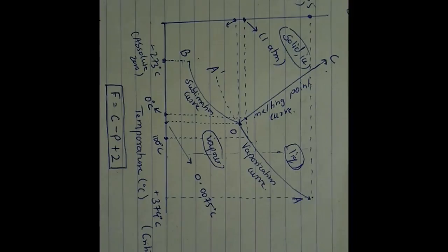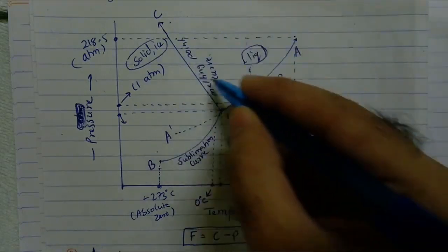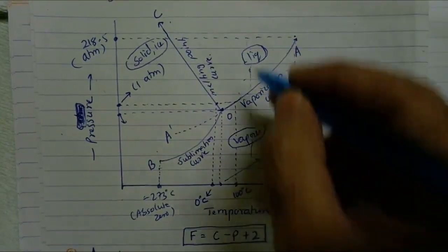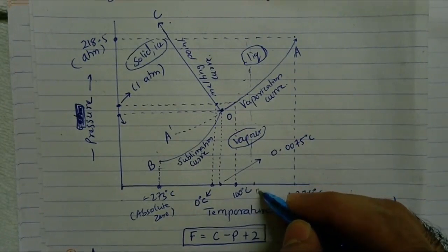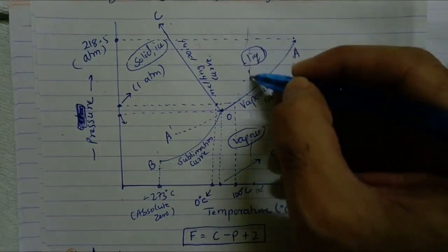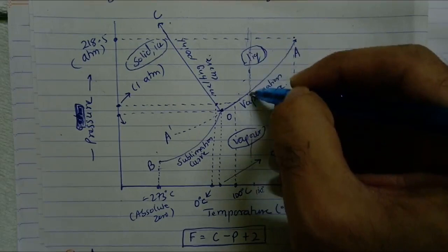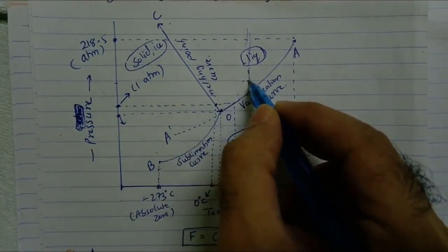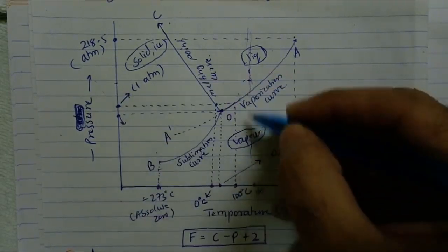Let us see now. Come to the diagram now. Suppose I want to define any point in this AOC. I told you already this is water in liquid form and this is one phase in this area. So if I want to define any point in this area, it requires at least 2 variables. How? Suppose if I give only one variable, let's say 120 degree, I will tell find a point at 120 degree. So 120 degree, this whole line from here to here, it will cover 120 degree. So you have to specify pressure also at what point. So here suppose let's say at 1.1 atmospheric pressure, so it will be somewhere here. So this is your point. So if you want to define this point, you require 2 variables. Is that clear? So that is why it is called a 2 variable system or bivariant.